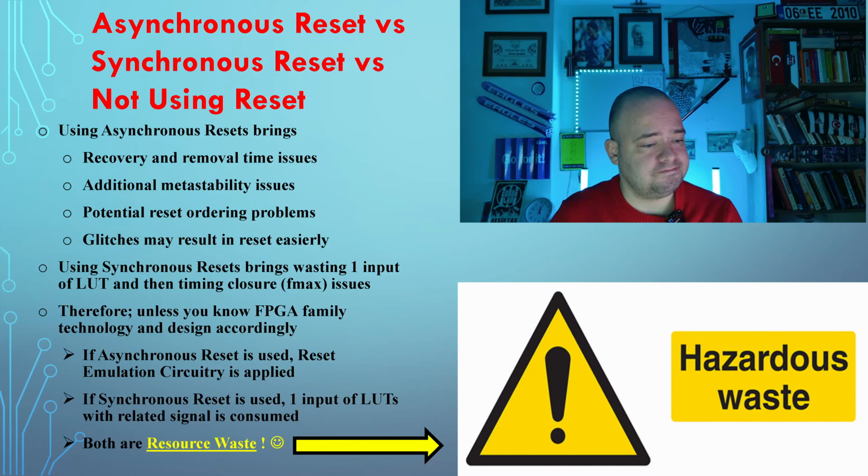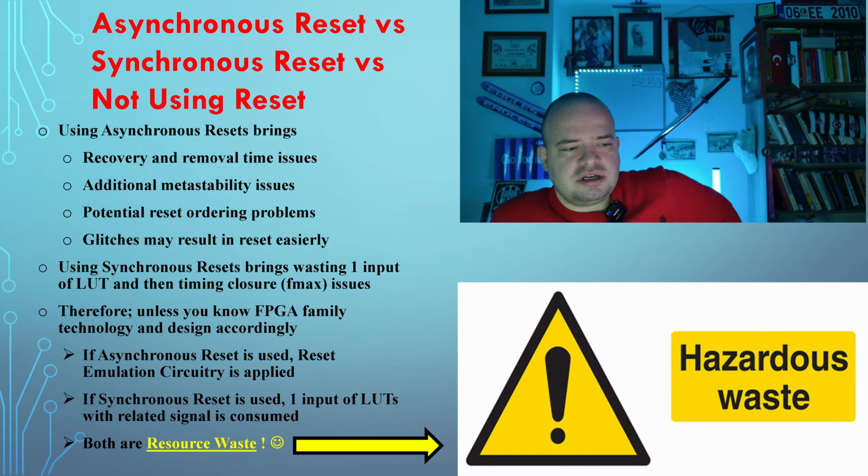At the reset synchronization process, the RST signal is an internally generated signal passed from flip-flops, or we use an external one. By the way, it could be incoming internally from a different clock domain, Furkan. Then you need to apply the same thing again. Yes, nice point. You are saying don't use external signals directly before synchronizing them. 100% correct.